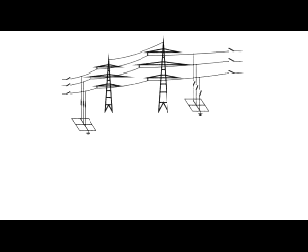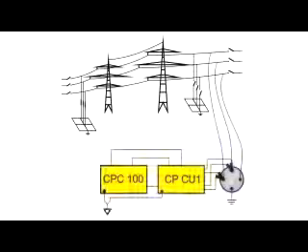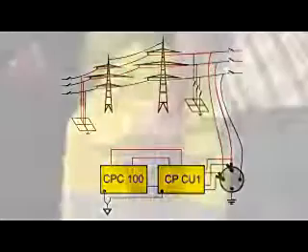The line is grounded at the far end, the CPC is connected via the CPCU1 to the overhead line to inject the current, the voltage is measured, and impedance and residual compensation factor are automatically calculated. The CPC can take measurements away from the power system frequency, hence reducing the power required to overcome interference from other substation plants. As a result, the size of the equipment is greatly reduced.